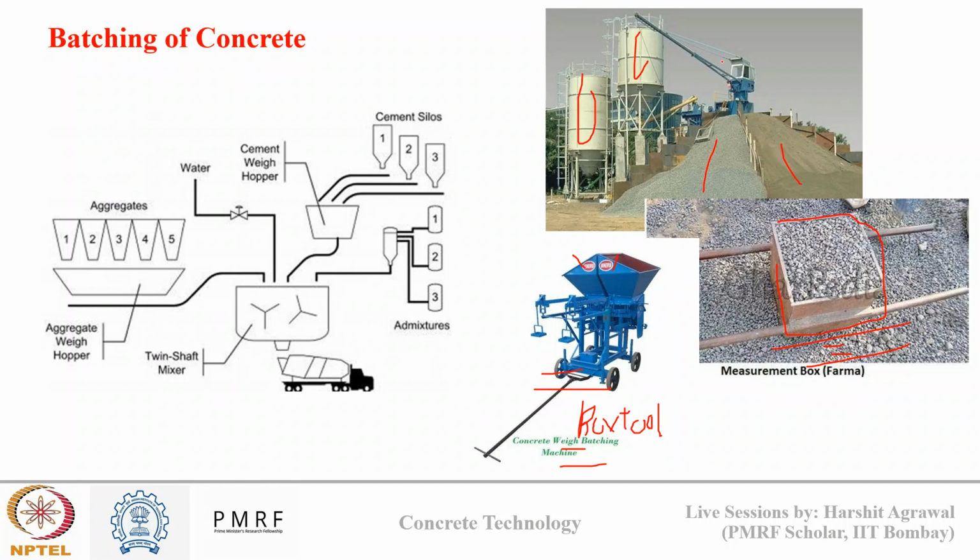And then at the top you can see there is a control unit which takes care of weighing, weigh batching and proportioning. The control unit collects all the different raw materials in specific proportion from unit storage, and pours them into a concrete mixer, which after mixing is ready to be taken to site to be poured in the formwork.